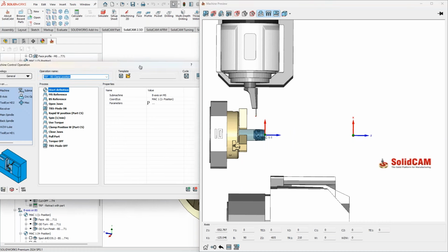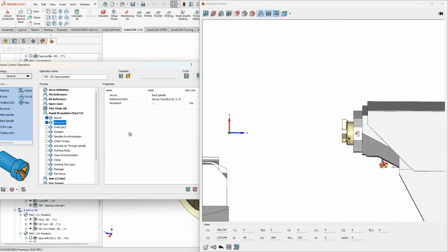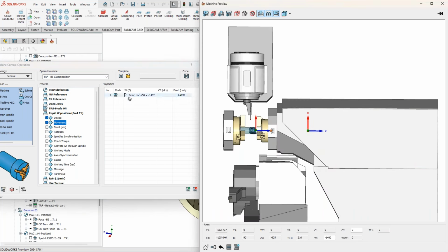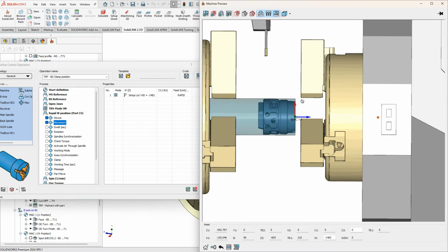Now, classic example, the way you were doing this is by using home reference values of the linear on the sub spindle. Usually G53, go with the rapid, then go slower, etc. So you can see it also over here. So you have the movement, and the movement is related to the machine coordinate system of this W axis. This is completely okay to do it in this way, yes.